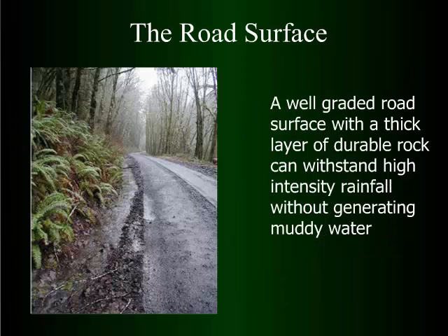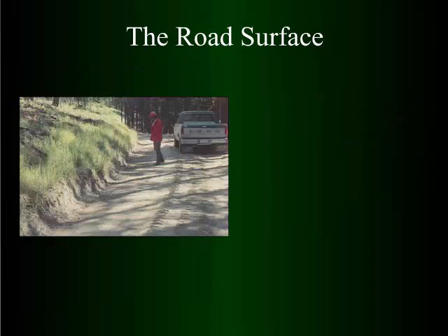Once again, we don't use that much rock, but where you do have it, the best protection for your rock surface is a good functioning ditch. And then you can see a little bit of crown on this road. Between a crown and the ditch, that's the best way to protect your rock. It just keeps the water from accumulating and keeps your subgrade from pumping. Previous example we've seen, no ditch.